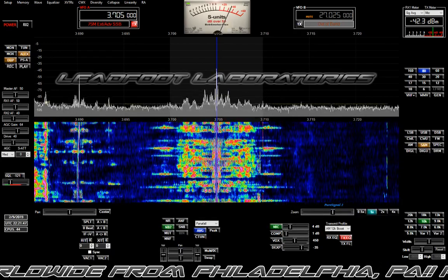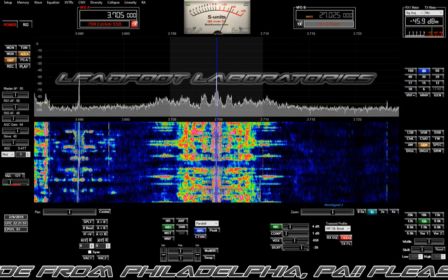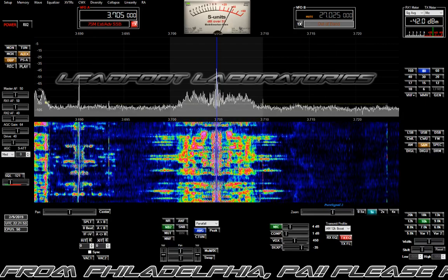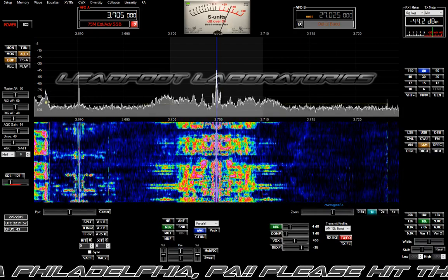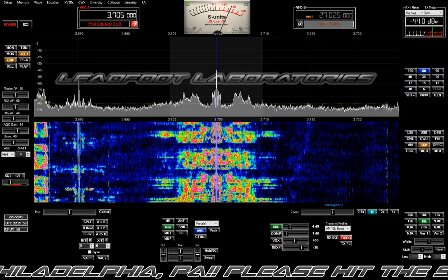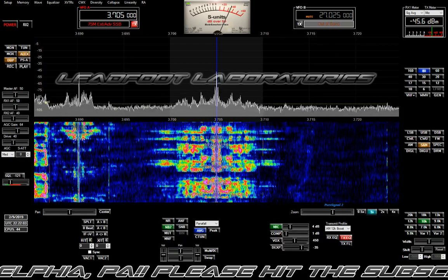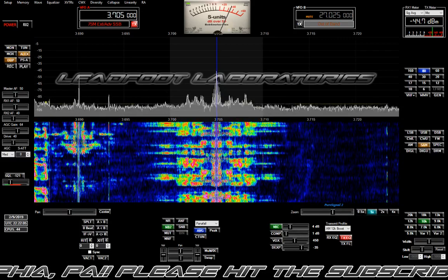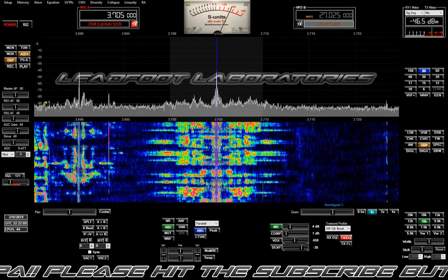And obviously, what it does is it looks at any nonlinearities within the transfer curve of the RF input to the RF output, and it analyzes the transfer curve, or the deviation from the ideal or best fit transfer curve,